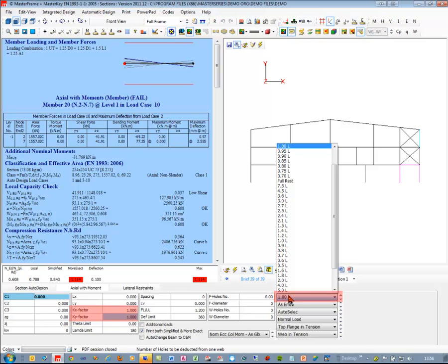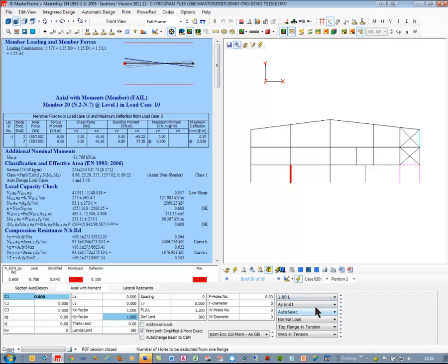So you actually have 3 effective lengths in essence when you're dealing with a beam axial with moment. You have your bending and you have your axial, and whether this is a beam or a column, if we're doing an axial with moment check, you do have both of those criteria, and that can be different from this. So I think that covers that for you, Richard.